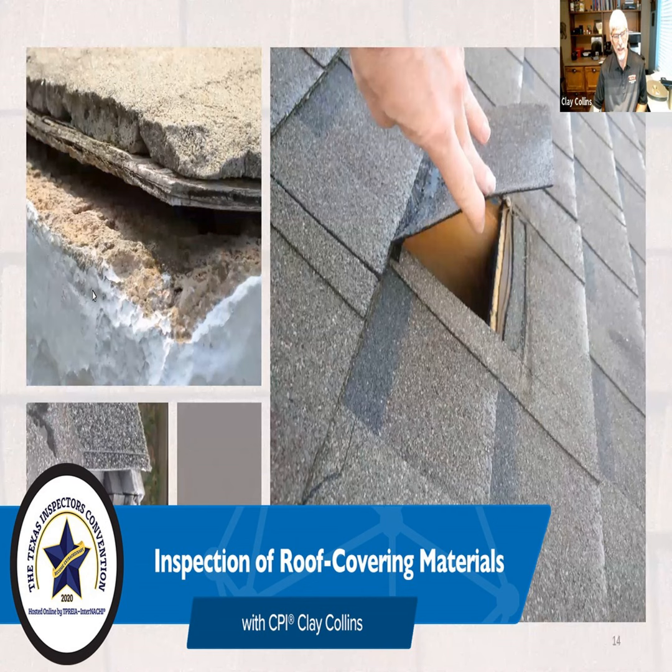But there is no mark along a cut shingle for where to nail it. You can buy a starter strip like this one where it tells you where to nail. And this is not a cut. This is sold as a starter strip. And I see down here, sometimes a homeowner will try to do something. They spend all their time trying to remove this strip. The only purpose of that is to keep the shingles from sticking together while they're in the bundle. And if it's not done right, if you don't have adhesion, you're going to have problems. Those shingles are just going to lift up.